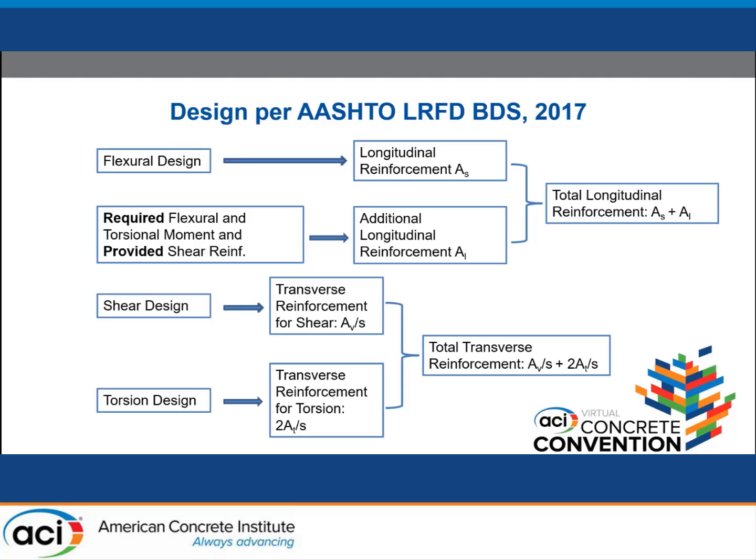One thing for AASHTO LRFD is that we do need to consider the flexural moment, torsional moment, as well as the shear to determine the additional longitudinal reinforcement required. There is an equation provided by AASHTO LRFD so that we can determine the total longitudinal reinforcement required. This is a typical procedure that you can use for cap beam design per AASHTO.